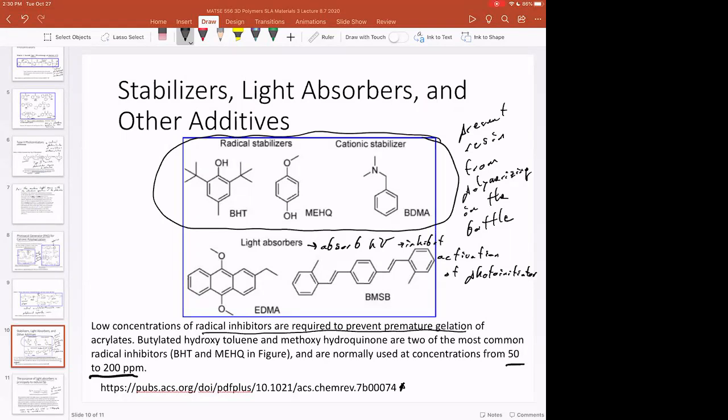And this is why a lot of these stereolithography resins are treated as hazardous or reactive chemicals, because all this stuff is still in the resin after you make the part. And so if you FDM a part out of PLA, PLA is a pretty benign plastic. It's not a big deal. It smells a little bit when it's heated up because of the additives that they put in PLA when you do material extrusion AM. But in general, thermoplastics are not too hazardous.